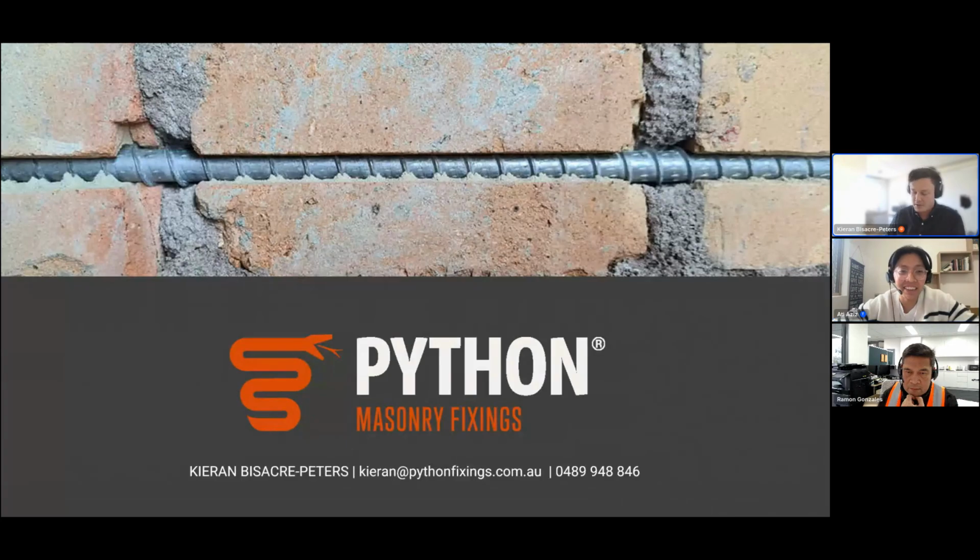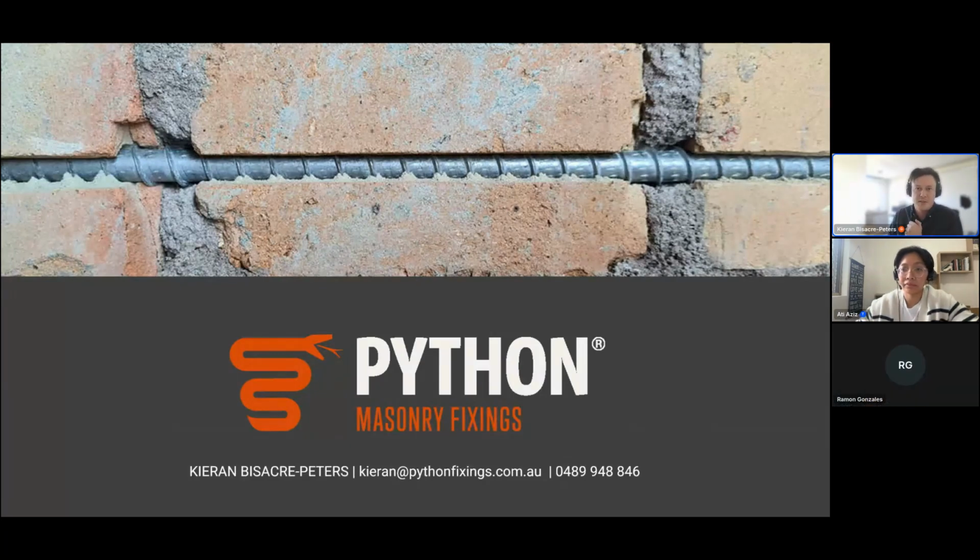Yeah, good question. In most instances for retrofitting wall ties for veneers and double brick walls, tie spacings from AS3700 and the National Construction Code will be adopted, which refers back to AS3700. There are a few instances, in particular we have developed a couple of systems which require closer anchor spacings. For example, when you want to compositely connect an outer veneer to an inner veneer so that it works together and gives you an increase in lateral capacity. In that instance, we go closer than the AS3700 maximum spacings. Again, I'd be happy to share that with you afterwards.